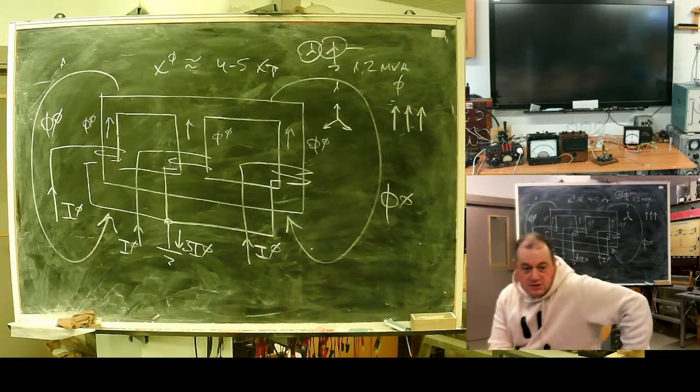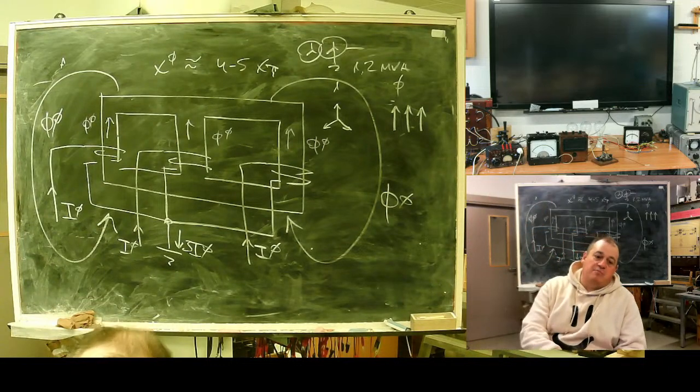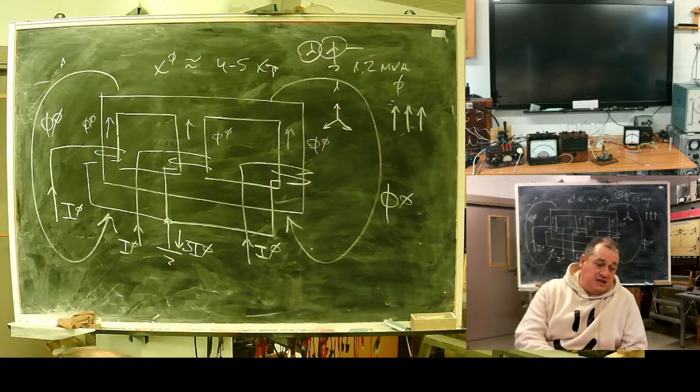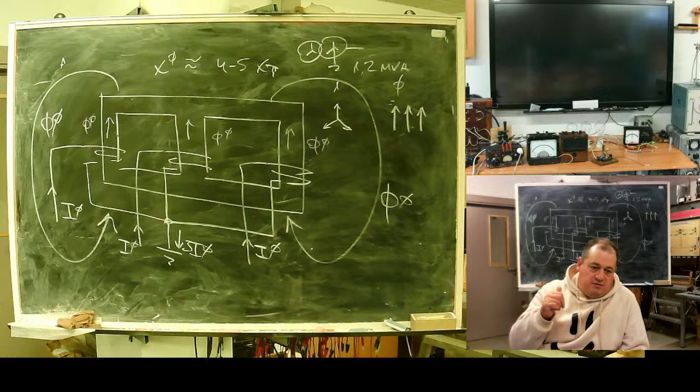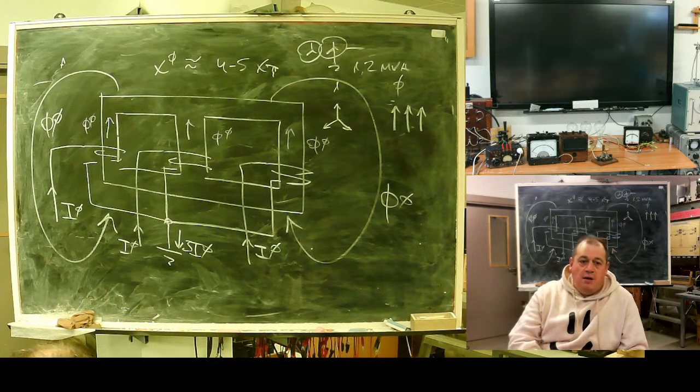If you need transformers, for example, 10 kV to 0.4, this will be the cheapest available on the market. But first problem: in case of load non-symmetry, you will have voltage symmetry distortion.